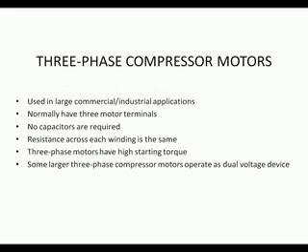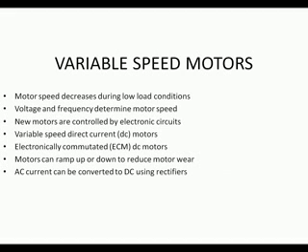There are some motors that are considered special application. They might have more than 3 motor terminals. Some have auxiliary compressor windings to increase the motor efficiency. Some motors have a winding thermostat wired through the compressor shell. Three-phase motors have one thermostat for each winding. The winding thermostats are all wired in series.